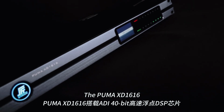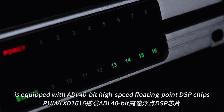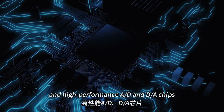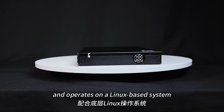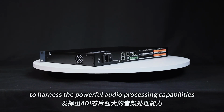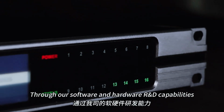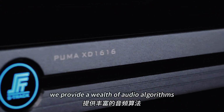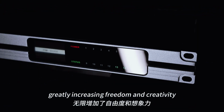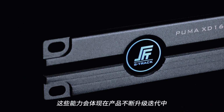The PUMA XD1616 is equipped with ADI 40-bit high-speed floating-point DSP chips, ARM chips, and high-performance A/D and D/A chips, and operates on a Linux-based system to harness the powerful audio processing capabilities of the ADI chips. Through our software and hardware R&D capabilities, we provide a wealth of audio algorithms, greatly increasing freedom and creativity, which will be reflected in the continuous upgrades and iterations of the product.